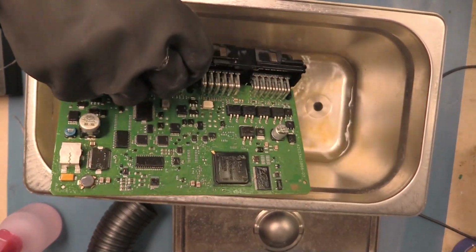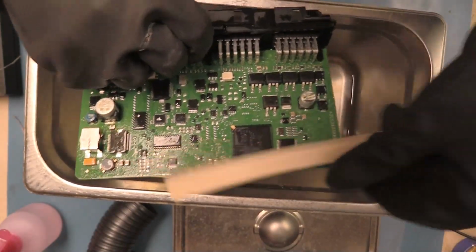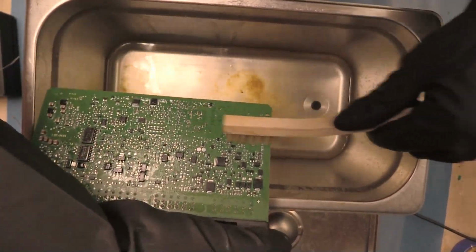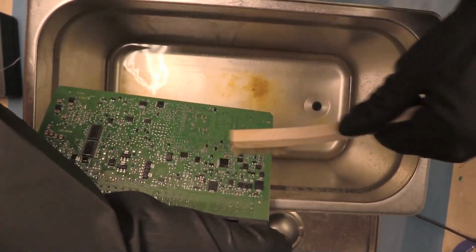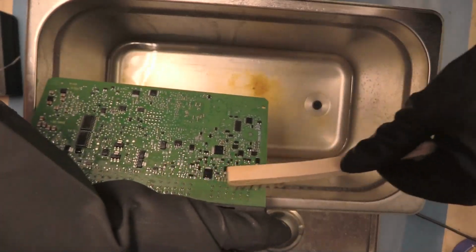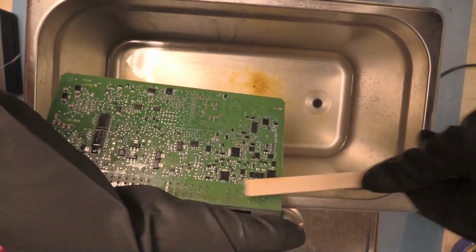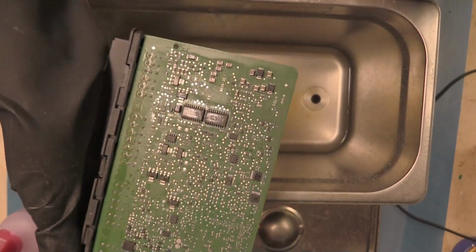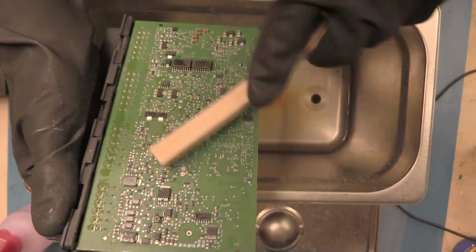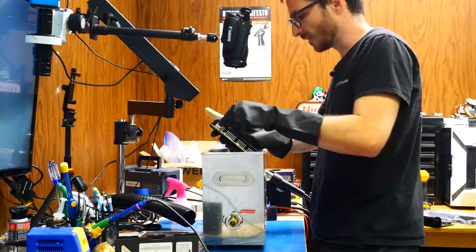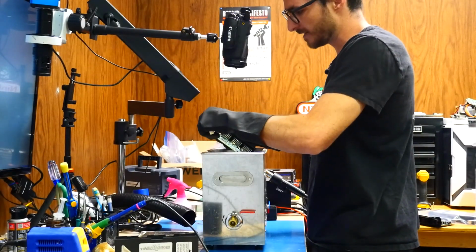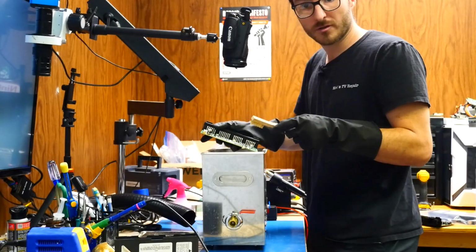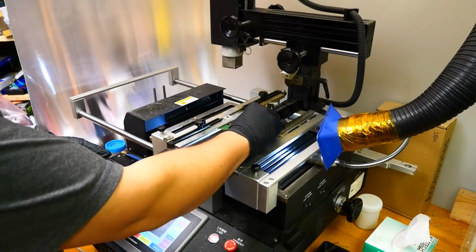Okay, the circuit board's been soaking again for quite a while. Let's give it another scrub and see what we get. Actually, I'm making a decent amount of progress here. Again, you don't want to scrub too hard, otherwise you risk knocking off components, and that's gonna be a whole different ball game of problems. Okay, and it looks like we almost got 100% off. We're at about 80 to 90% off, and I think that's gonna be good enough, so we're gonna call it good here. We're gonna give it an isopropyl alcohol bath to clean off some of the residual chemicals, and then we'll go ahead and put it on our machine for repair.